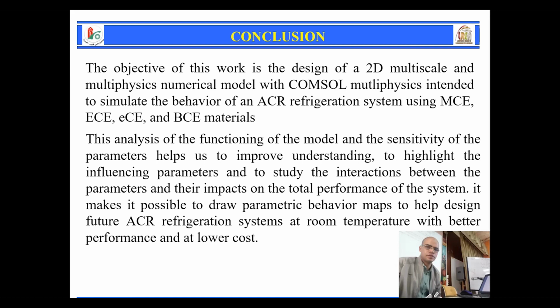This analysis of the functioning of the model and the sensitivity of the parameters help us to improve understanding, to highlight influencing parameters, and to study the interaction between the parameters and their impact on the total performance of the system. It makes it possible to draw parametric behavior maps to help design future ICR refrigeration systems at room temperature with better performance and lower cost.